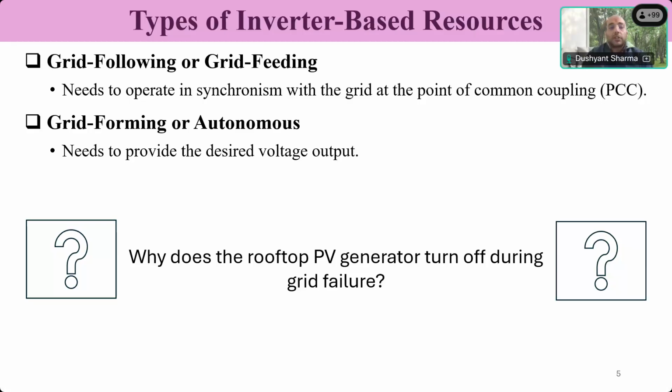But ideally a voltage source can have its own voltage. So if I have to connect a source which is with me in my home to a wall socket, how would I connect? I have to ensure that its output voltage is also 230 volts only. Then how do I vary the power? By changing the current, because I can inject current into the network. But still the voltage will remain 230 volts, which is the grid voltage.